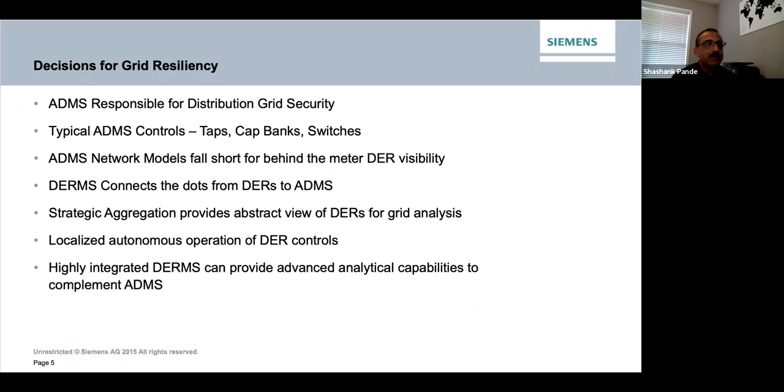In fact, even now, most of the talk is about how big a problem it is to have so many DERs on the grid and so much generation coming up on the distribution side. Hussein also mentioned that reverse power flow is a problem. I will say it's a problem pretty much everywhere. Utilities have to change things, and it's pretty expensive to change the protection schemes to accommodate these DERs, and that remains a technological challenge that is actually solvable, but it is there.